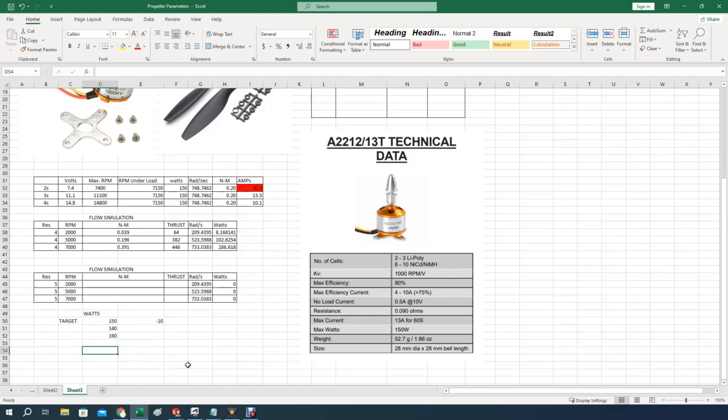So this is what we're going to do. We're going to set up an optimization process in SolidWorks to get this done. How do we do that? First of all, we don't have that watt equation that is calculated here. You can see I need to multiply whatever is calculated on D, that's this value here. Whatever torque, I need to multiply the torque by the radians per second to get watts, and that will do.